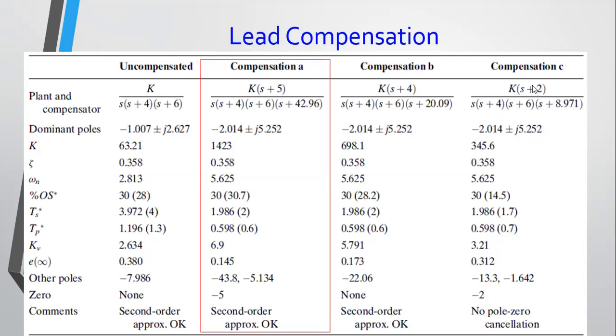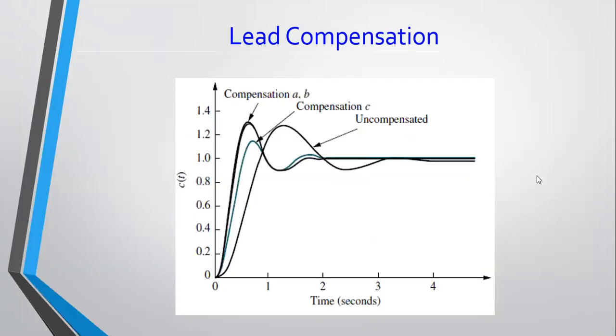So you can see here, by doing compensation using different positions for your zeros, that's fully permissible, but you have to cross-check in simulation: are you getting the transient response you want? For each 0 you're introducing, of course, the pole that you need to introduce for that lead compensator would be different. So you can just work it out using the method we've done.